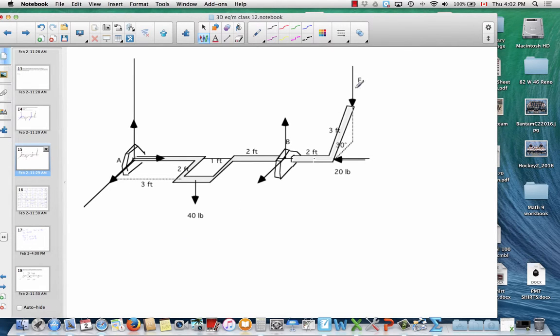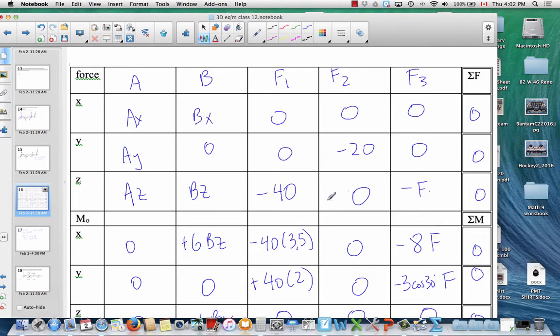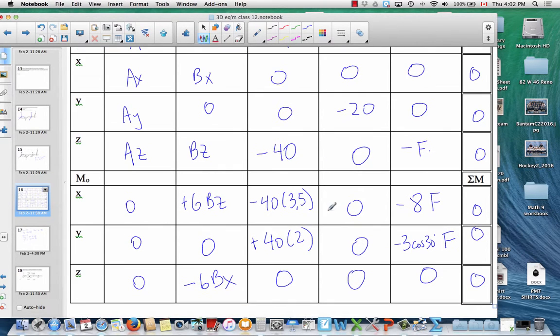So there's actually two moments of this force. You could just do R is 8J minus 3 cos 30I, and then you could take the cross product with F. That would be another way of doing it. So you could use your R vector is 8J minus 3 cos 30I, and then just cross that with the force, which is F in the minus K direction. So here's the chart. Scroll down, check and see how you did.